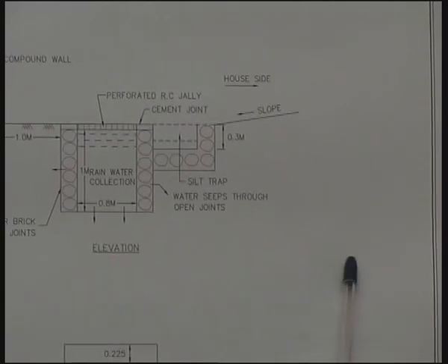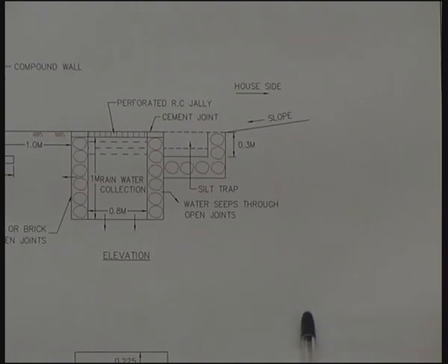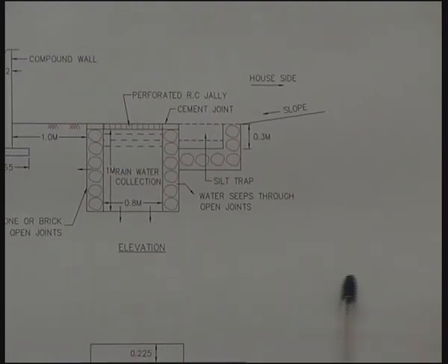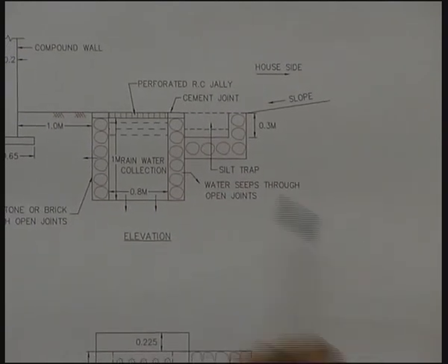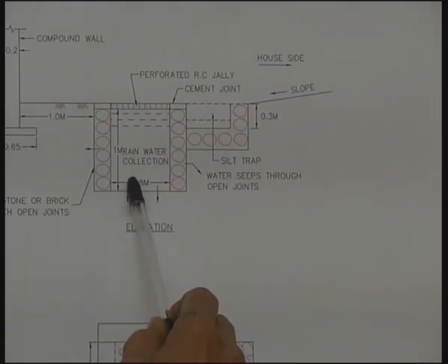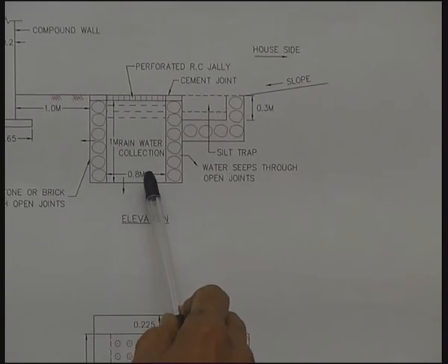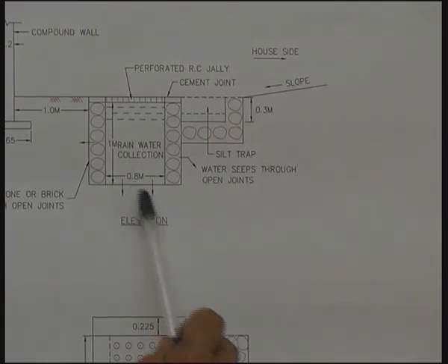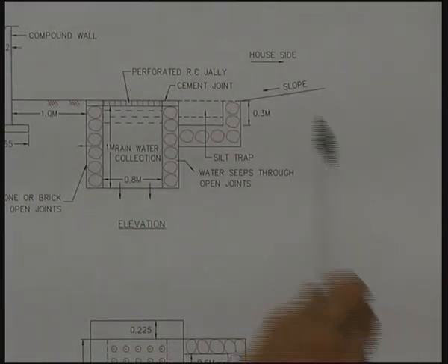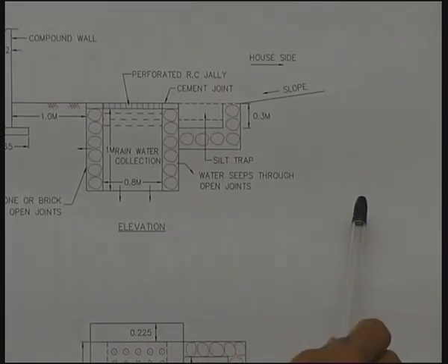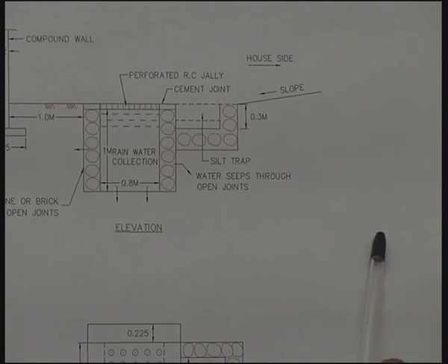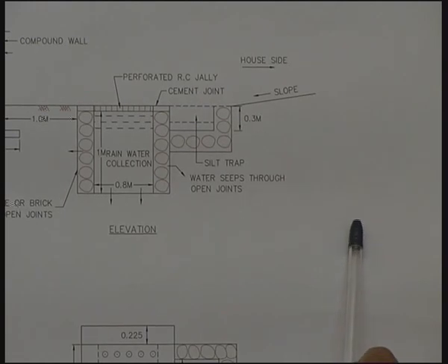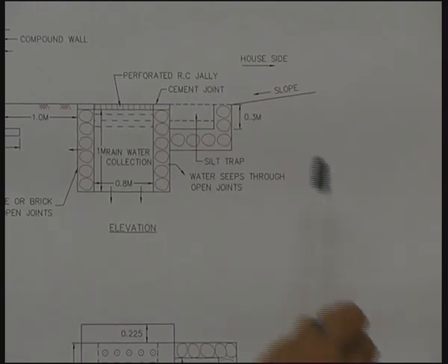The foundations of the column should not have any cavity within that bulb of pressure zone, what we call the bulb of pressure zone. So now this cavity is not in the bulb of pressure zone of the foundation, it is away from the foundation and it is at a higher level than the foundation level. So there is no problem of interfering with the foundations and causing instability with regard to the structural details of the foundation.